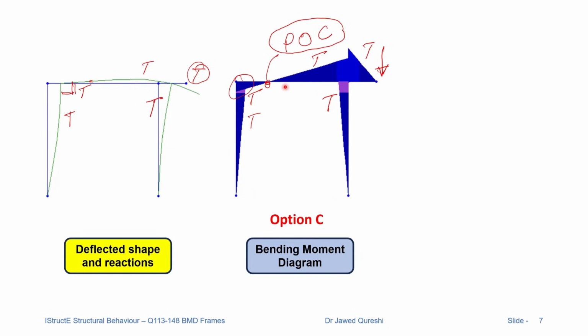The leftward reaction will create this bending. And for the beam, we have moment over here. To obtain this moment on the sagging side, we should have a downward vertical reaction. And for the other part, because we have a point load at the end, to obtain this bending behavior, we should have an upward reaction over here. Let us mark these reactions.